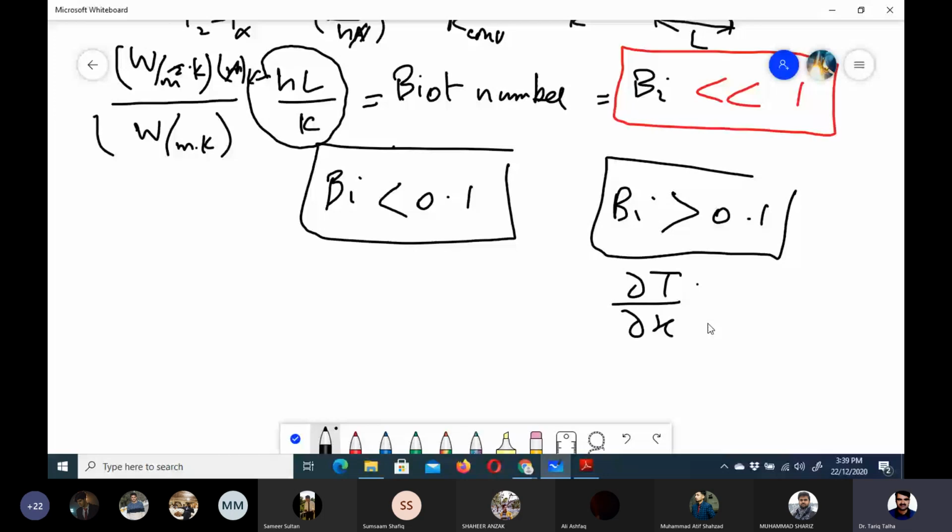But because I have already given you a project, you don't need to go through that. We would restrict ourselves only to this lumped capacitance method. So if there is a transient problem in which there is a spatial gradient of temperature as well, then we either need to use some complex analysis, or we use that commercial software. Because we have been given that project, you can explore different options for that. So Biot number should be quite less than 1.